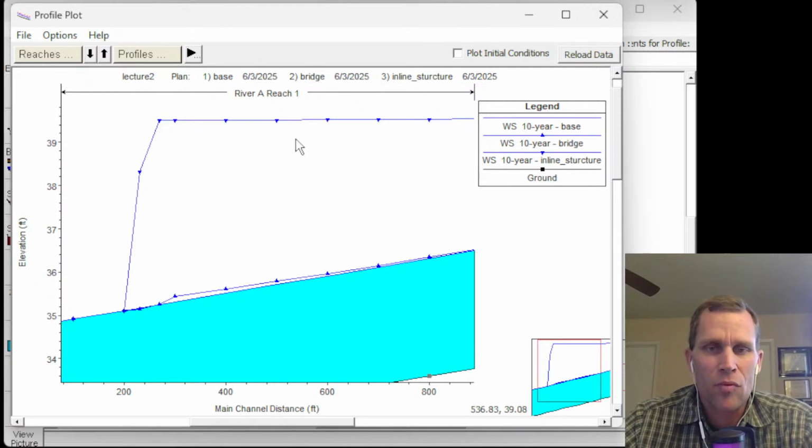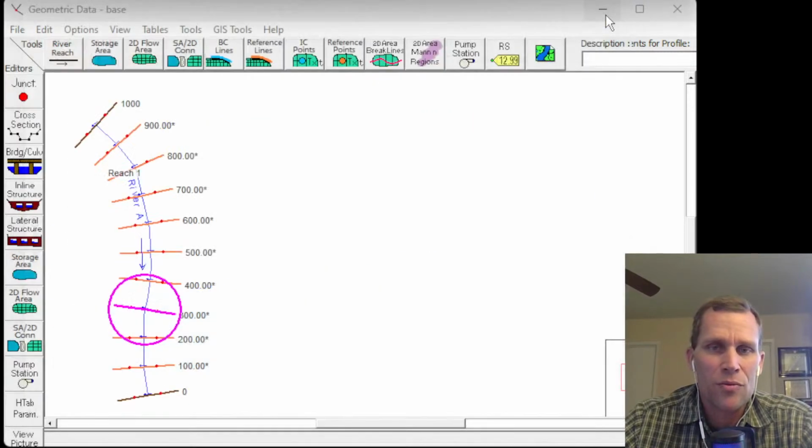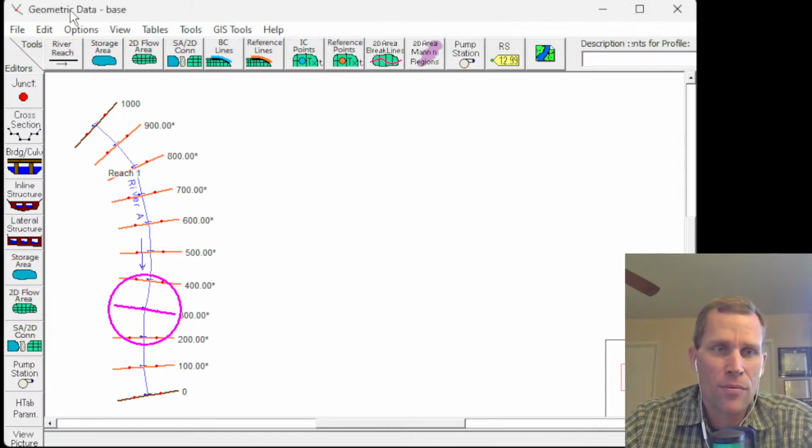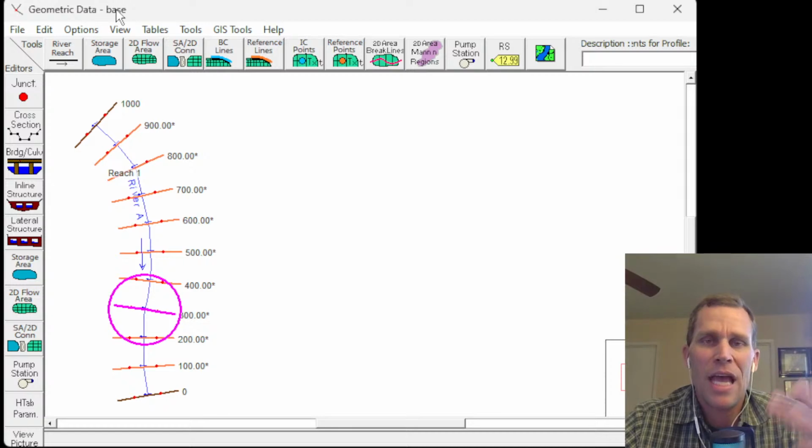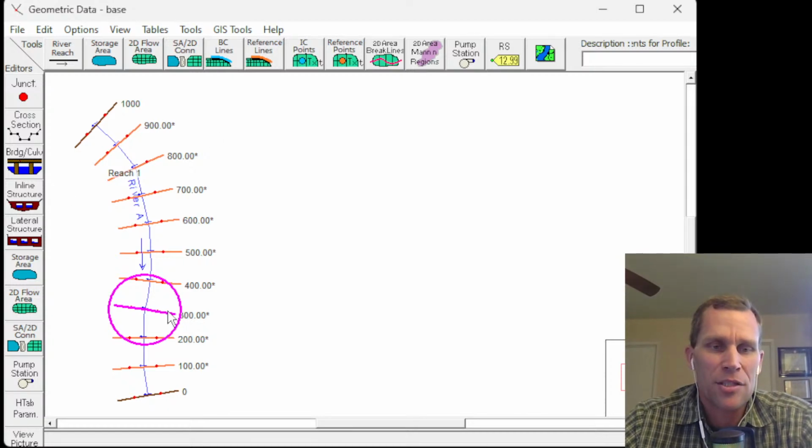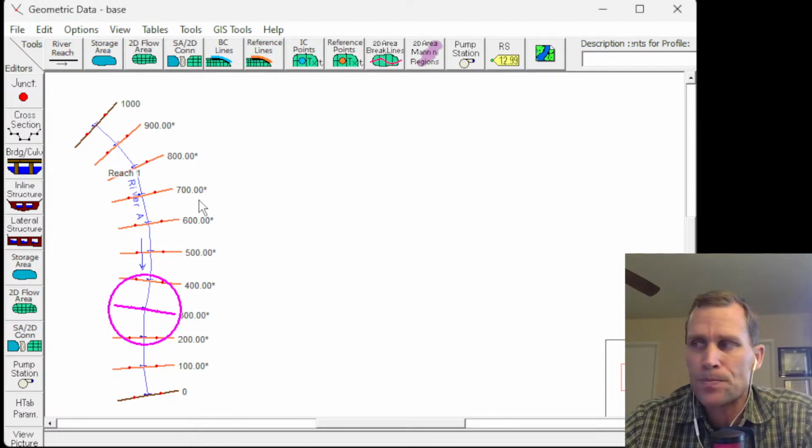But yeah, just wanted to finish up this lecture by saying thanks for joining me. What we did was we added a tributary flow and later looked at a diversion split flow scenario, ran the simulation. And then after that, we created 3 geometries. Of course, we started with the base geometry, but we created a bridge and an inline structure, ran a simulation, a constant, steady 1D flow of 400 CFS, and then looked at those results.